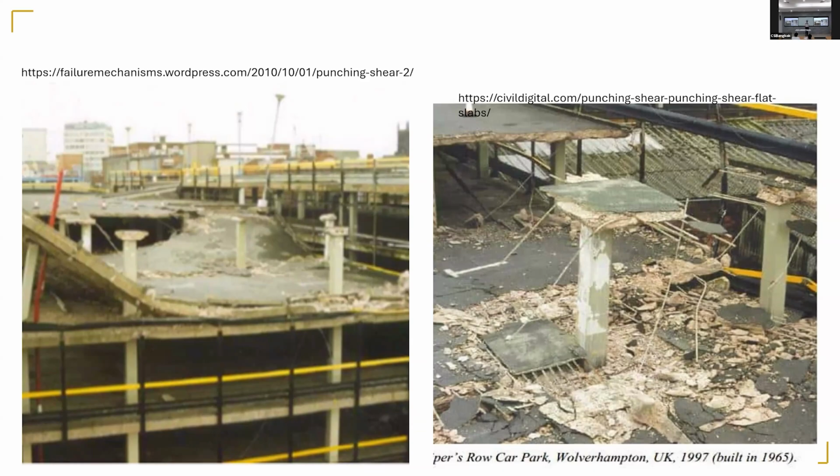So there is extra reinforcement to be put at the bottom of the column, not on the top, because the top breaks. The bottom reinforcement is not required by analysis. You don't need bottom reinforcement over the column because the moment is negative. So nobody provides any reinforcement at the bottom on the column. They said, no, you must provide very large diameter, 3 or 4 bars at the bottom of the column, enough to carry the whole slab if it fails by hanging, so it doesn't fall down.